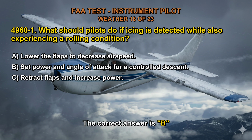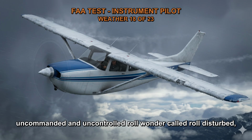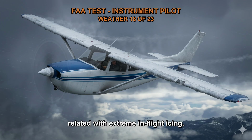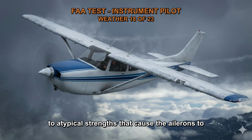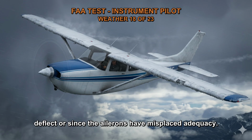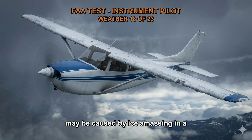The correct answer is B. One risk of structural icing is the possible uncommanded and uncontrolled roll phenomenon called roll upset, associated with severe in-flight icing. Roll upset may occur as a result of, or prior to, a wing stall due to abnormal forces that cause the ailerons to deflect, or because the ailerons have lost effectiveness. Deflection of the ailerons or loss of aileron effectiveness may be caused by ice accumulating in a sensitive area of the wing aft of areas protected by wing ice protection systems.